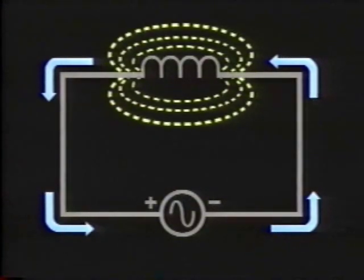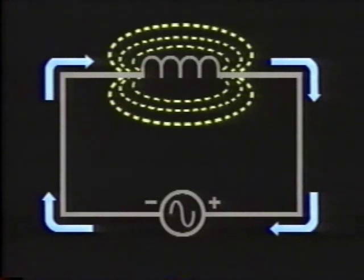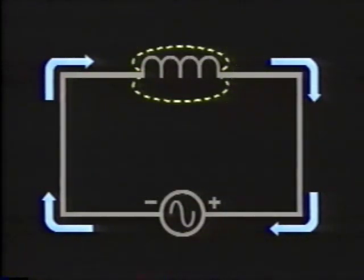To summarize, the inductor alternately draws energy from the source and then returns the energy that has been stored in its electromagnetic field back to the source twice each cycle of AC. Since the net energy drawn is zero, the power consumed by the inductor in this circuit is zero.